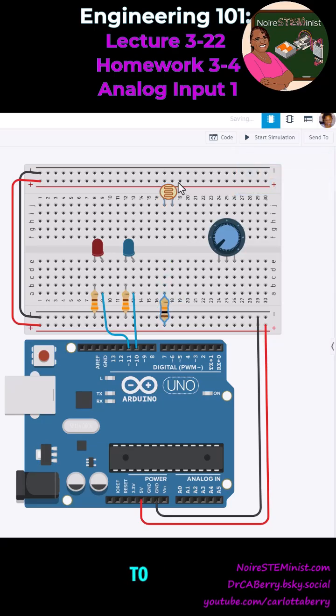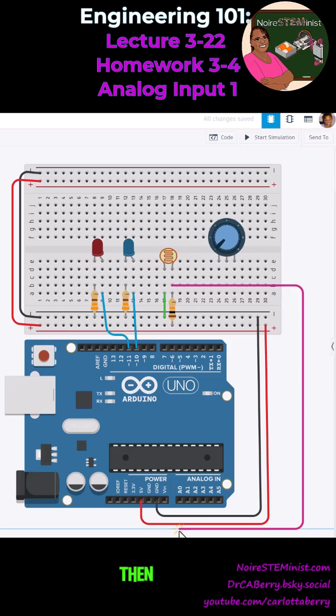So I am going to attach a 10 kilo ohm resistor to one leg of the photoresistor and to the 5-volt bus, and the other side of the photoresistor is going to be attached to ground. Then I'm going to take a wire from the meeting point of the photoresistor and the 10 kilo ohm resistor, and I am going to attach that to A0, which means an analog input on our Arduino Uno.